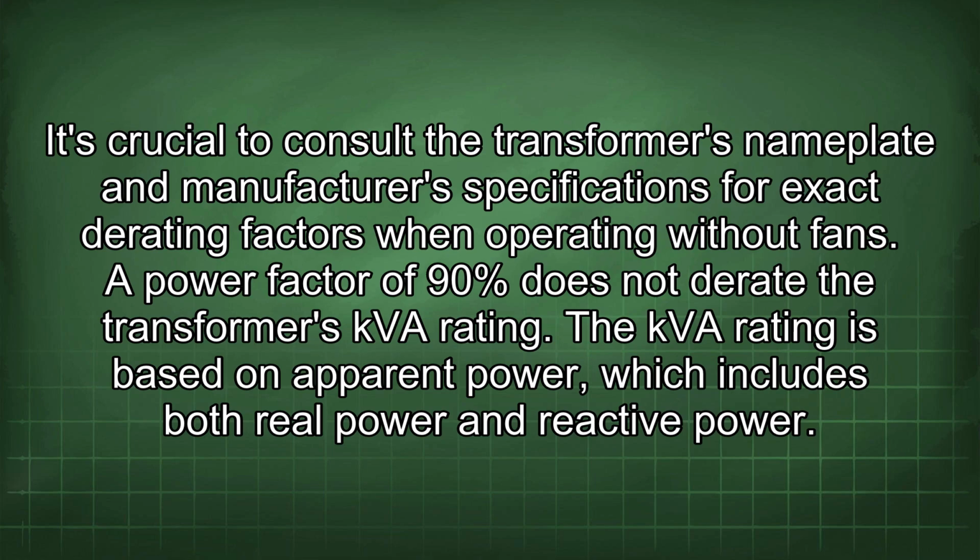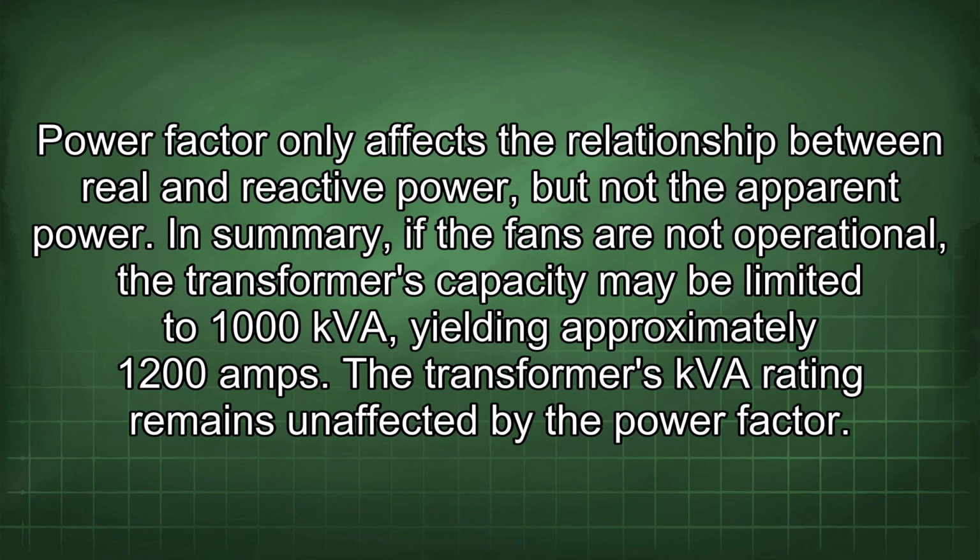A power factor of 90% does not derate the transformer's kVA rating. The kVA rating is based on apparent power, which includes both real power and reactive power. Power factor only affects the relationship between real and reactive power, but not the apparent power. In summary, if the fans are not operational, the transformer's capacity may be limited to 1000 kVA, yielding approximately 1200 amps. The transformer's kVA rating remains unaffected by the power factor.